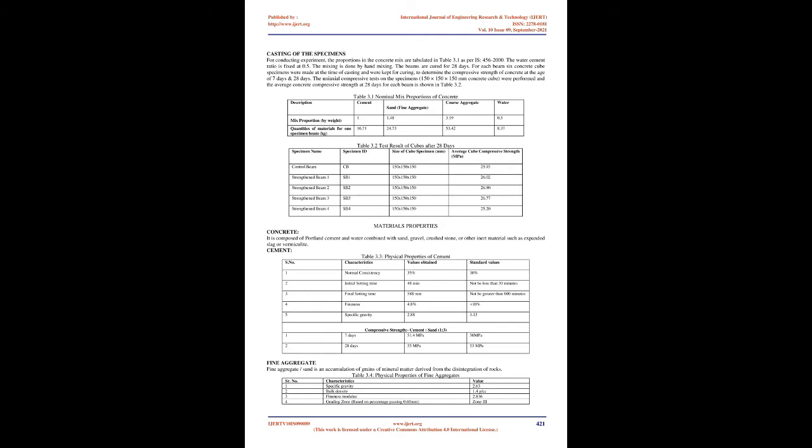Bond failure. Bond failure is governed by the properties of the weaker materials in contact, i.e. concrete and adhesive. When the shear strength of one of these is exceeded by the force, then transfer cannot be ensured anymore and a slip is produced. The debonding can take place in the concrete, between the concrete and the adhesive, in the adhesive, or between the adhesive